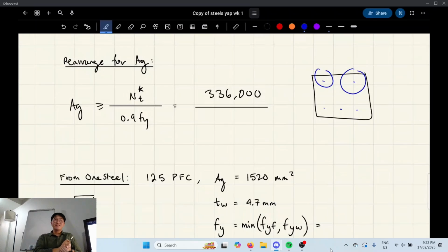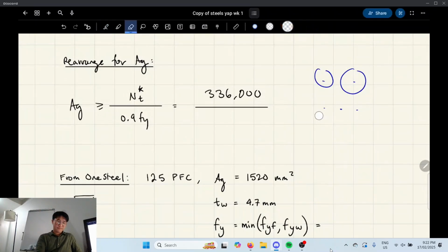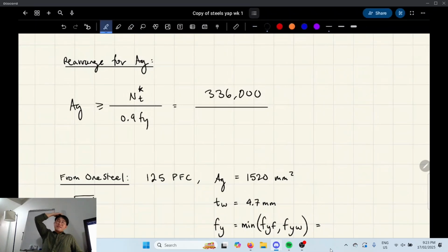Buckling only happens in unsupported lengths, like between two floors of a building. Steel can break in compression easily, but concrete can break in tension easily. Steel, without buckling, has the same strength in tension and compression, but concrete breaks very easily in tension. The steel helps the concrete in tension.